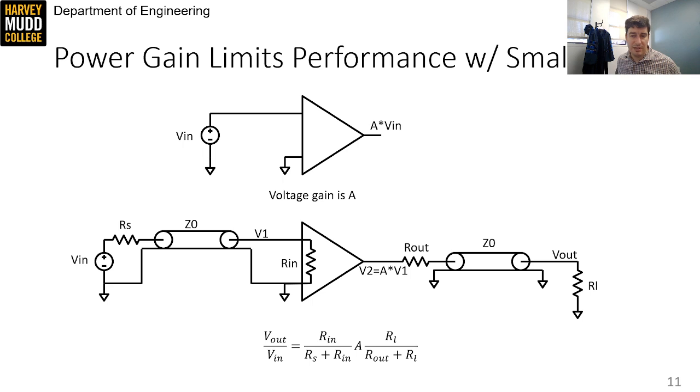But your next question might be, why isn't loaded voltage gain a good enough metric? Why go to power? And there are several reasons. As I mentioned above, power gain is convenient for many analyses because we can simplify our analysis by thinking about gain magnitudes and discard phase information. Power gain is also useful when the input and output have very different impedance levels. And finally, power gain lets you capture information about gain even when your signals are currents and your gains are current gains. So it's a universal language for a lot of types of circuits. And that's particularly important because voltages and voltage gains are often small at high frequencies, which makes them hard to measure.